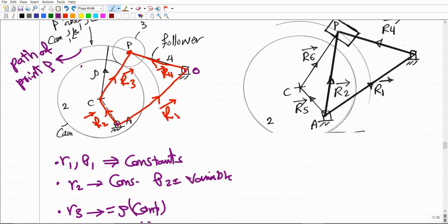But if this cam for some reason is fixed, then definitely there is no carrier acceleration. So you can solve this problem as a rolling contact problem, as long as this cam is fixed, because there is no carrier acceleration. But if we decided to work over this problem with two movable objects, the follower, the roller, and the cam, everything is moving. So definitely there should be carrier acceleration showing up here, and I'm going to show you where the source of this carrier acceleration is.